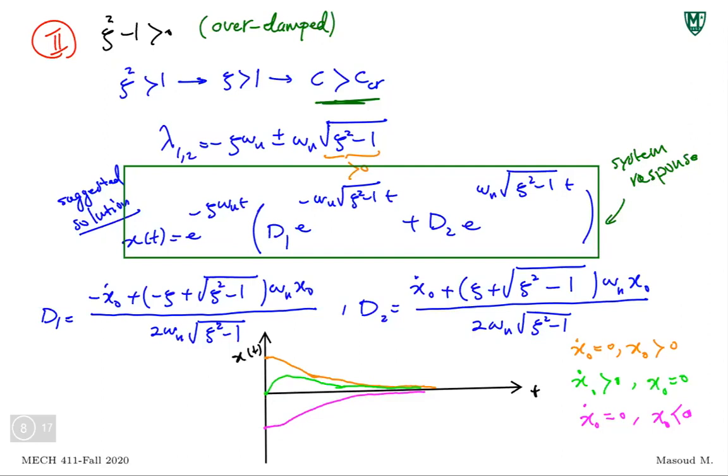A very good example of an overdamped system you can imagine is a bathroom door. At the top there is a system of a spring and a damper, but the damping is very strong. You've noticed it doesn't matter how hard you push, that door is not going to oscillate back and forth. As hard as you push it, it goes somewhere, you open it, and then it slowly comes back to where it was.